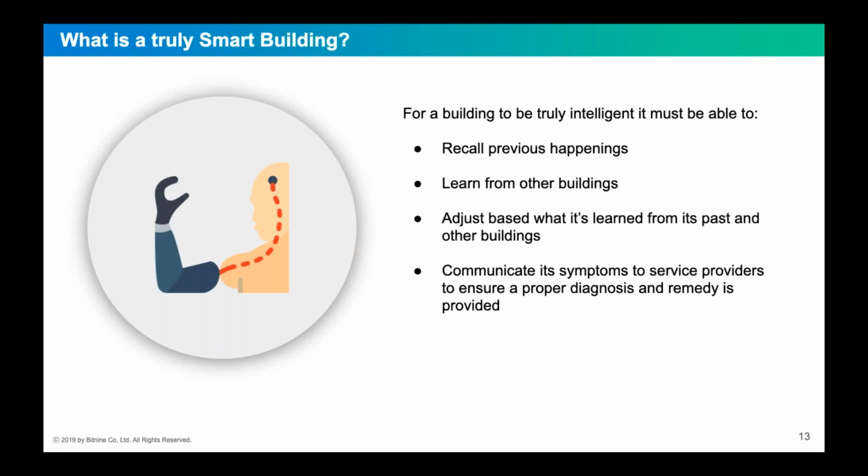And also, to your point, most service calls are driven by an effect that's occurred in the building, right? I am hot, I am cold. This operating room can't be used because the air pressure is not in a spot to prevent the contamination of other spaces through infectious disease that could be sitting within the air. So there are typically things that are occurring before that happens. The compressor starts to short cycle, or there's no hot water coming from the boiler, or name your different problem.